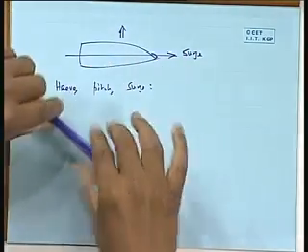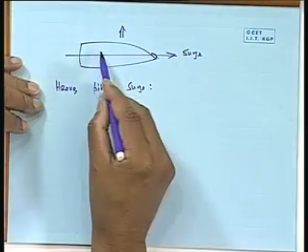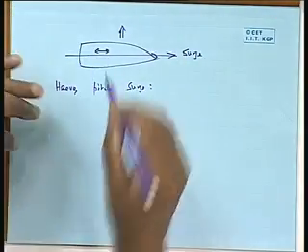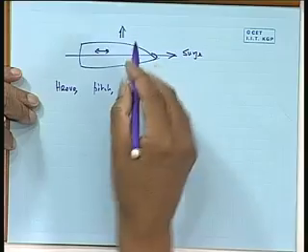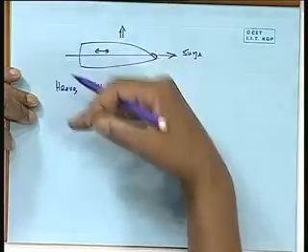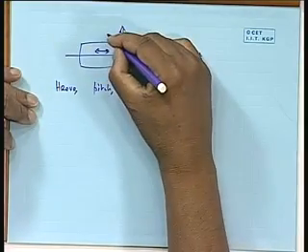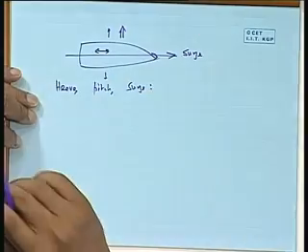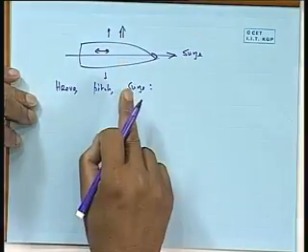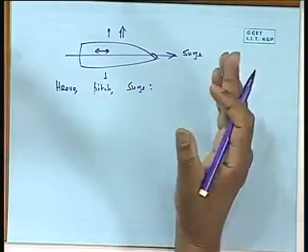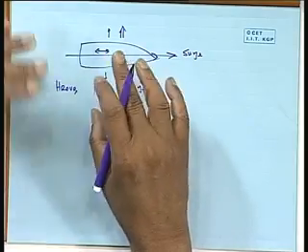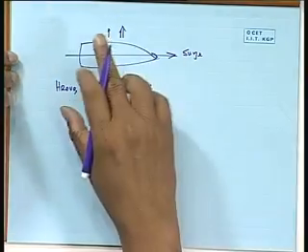Supposing the body is symmetric. If I move it this way, that way, will it cause any force this side? No, because it is exactly symmetric both sides. Whatever I do, suppose the fluid gets pushed, equivalent fluid gets pushed here. So the net force in the y direction because of x direction motion is 0. This is called having no coupling between sway and surge.